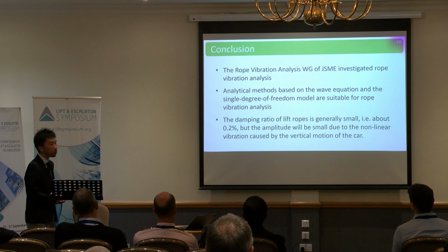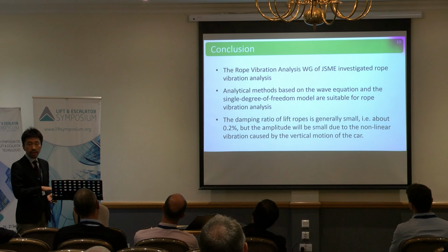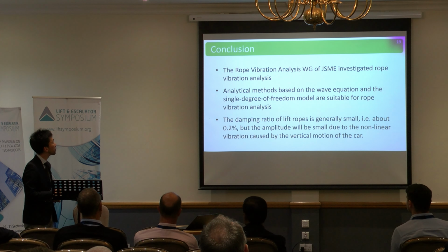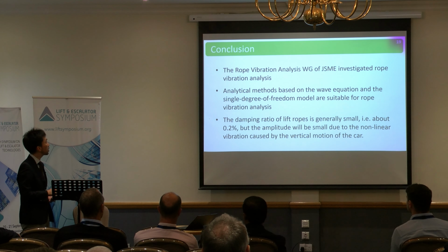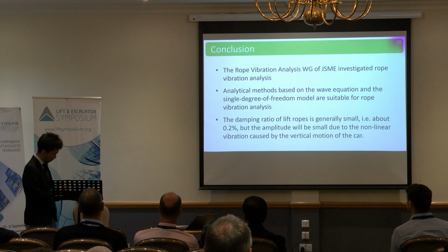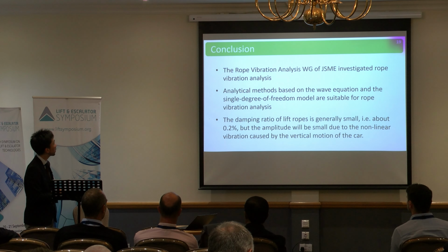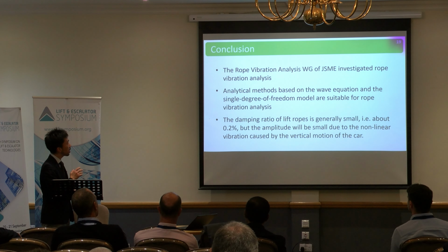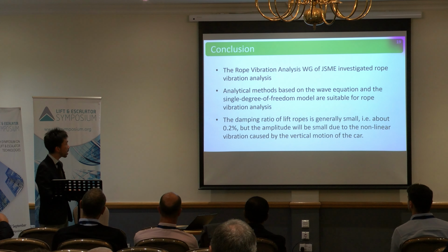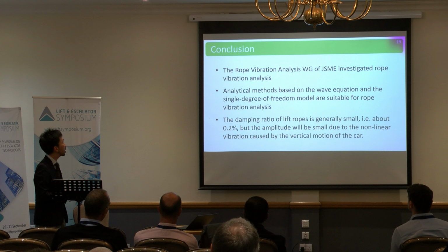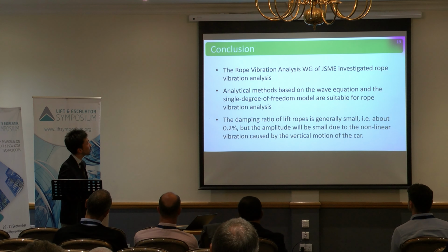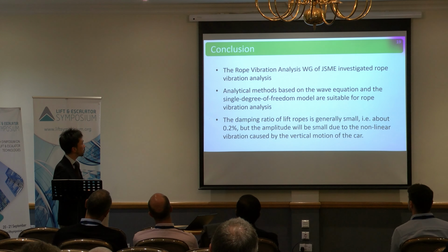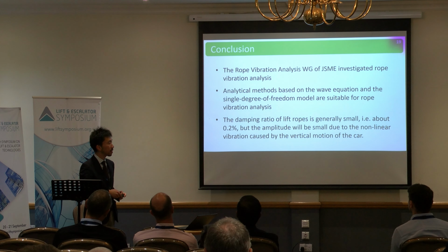So finally, I'd like to conclude my presentation. In this presentation, I talked about the activity of the rope vibration analysis working group, and we found that the analytical method based on the wave equation has very high accuracy, and also the single degree of freedom model is applicable for rope vibration analysis. And the damping ratio of lift rope is very small. Thank you very much. That's all.